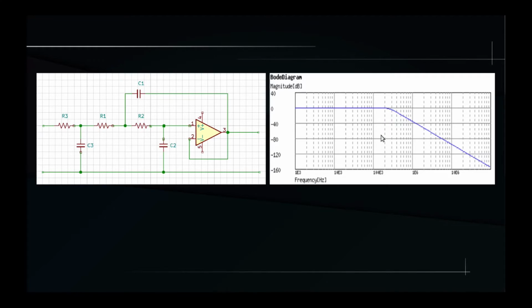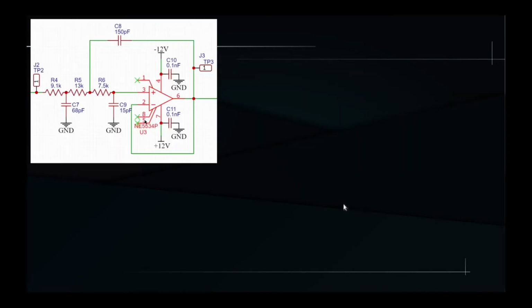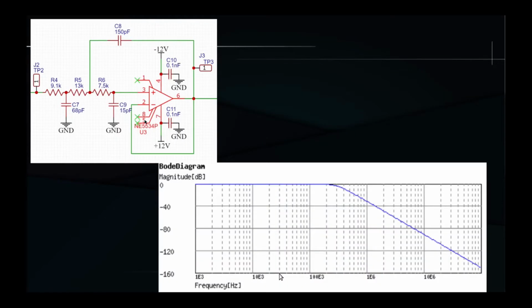Now that you have a better understanding of the filter theory, let's go back to the schematic of our filter for the theremin, and let's take a look at its magnitude Bode diagram. We can see that the region where we want to use this filter to achieve a good ratio between amplitude and frequency variations, while keeping the signal at a reasonable amplitude, is around 250-300 kHz, just about the cutoff frequency.